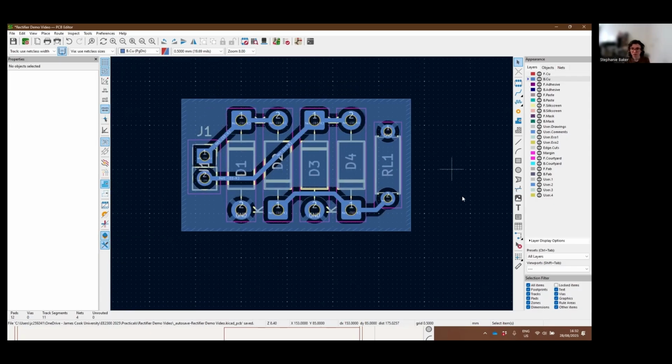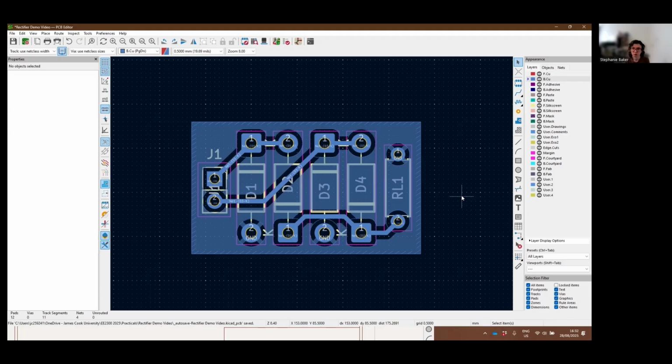Well, for a small circuit, for a simple circuit that's low frequency like this, it's mostly just because it is easier. So it's convenient to pick a ground reference where we've got lots of things connected, because then we don't have to connect this one to this one and add a whole bunch of extra tracks. So it's convenient in terms of layout. It does improve the electrical characteristics of the board, because instead of having a lot of tiny little tracks with tiny little resistances, you've just got this nice big flat copper plane. The other advantage for the subject is it just makes it a little bit easier for measurement, because then you have a whole plane on which to put one probe while you probe around with the other probe to measure different things. So that's nice as well.